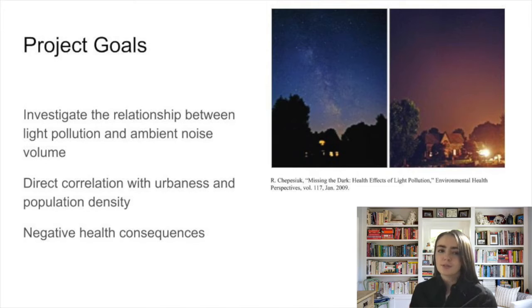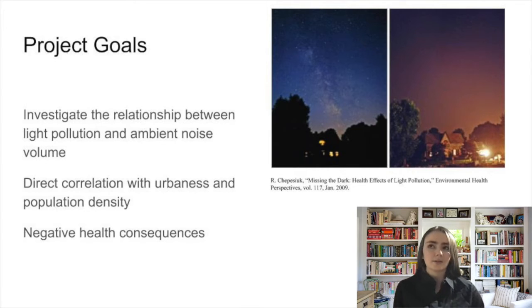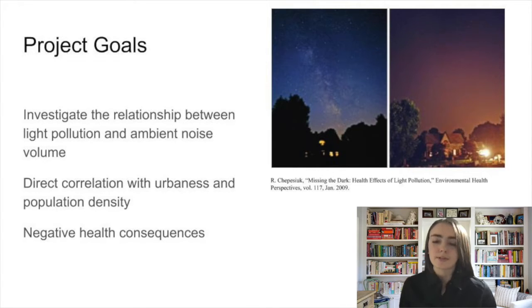So noise pollution is a result of industrial activities, commuting, air travel that contributes to the overall loudness of ambient noise in an area. Light pollution has several variants. We cared about sky glow in particular as a quantifier of pollution, which was defined as scattered light in urban areas resulting in a glow. Illuminance is the flux of light intensity. Its SI units are lux.